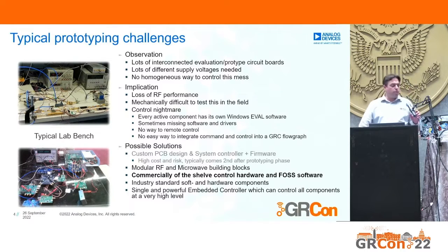So there are a number of possible solutions. One is to do a custom PCB design with a system controller and some custom firmware, but that's typically high cost and high risk, and it typically comes second after the prototyping phase. So in this presentation, we want to use commercial off-the-shelf control hardware and open source software, in this case, Linux.